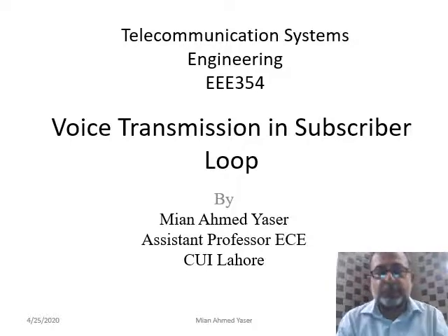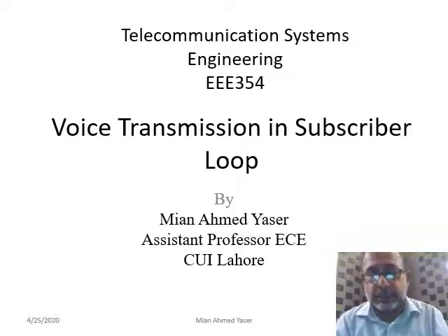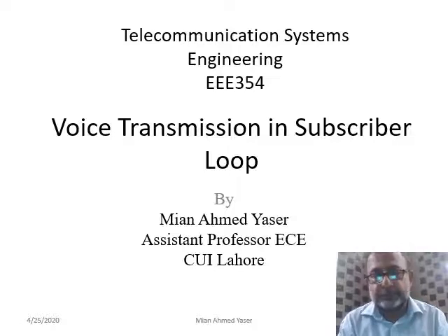Then it is observed and experienced that we do not require to send the complete 0 to 20 kilohertz band for a single voice. Even 0 to 4000 hertz can be sent for that purpose.